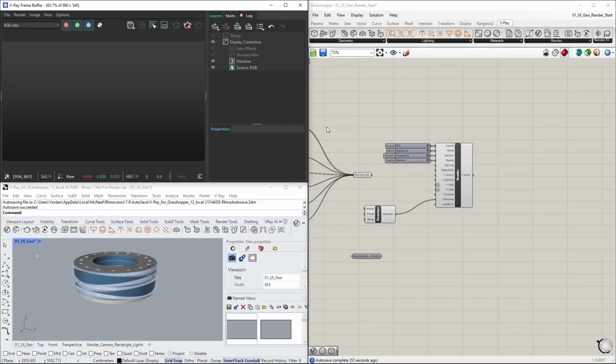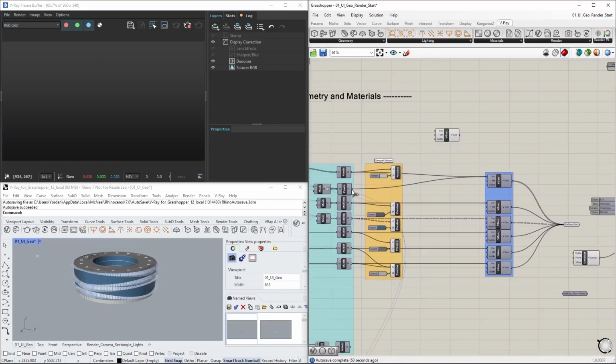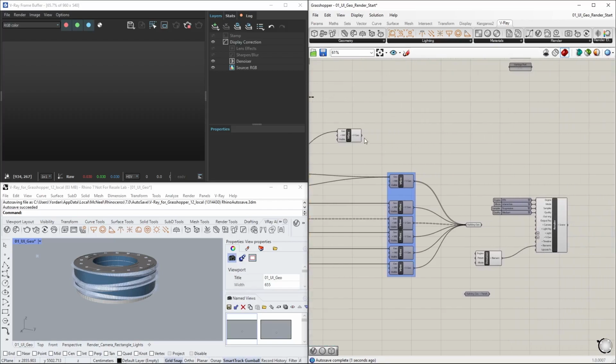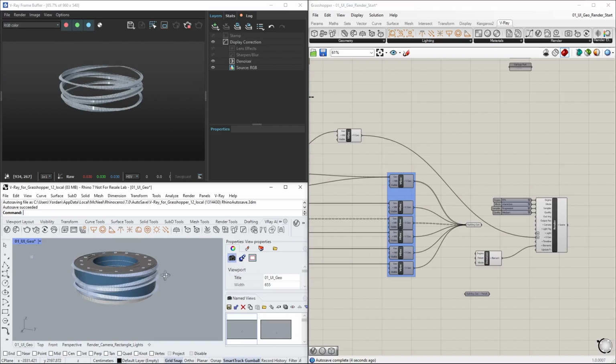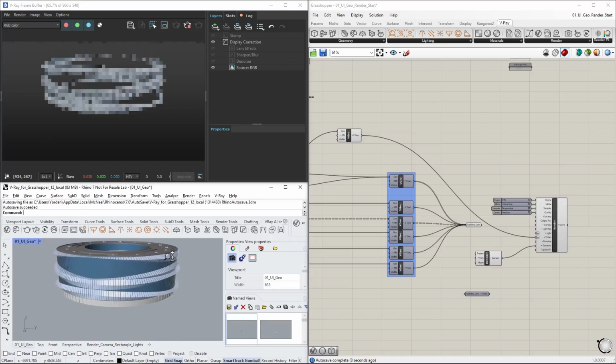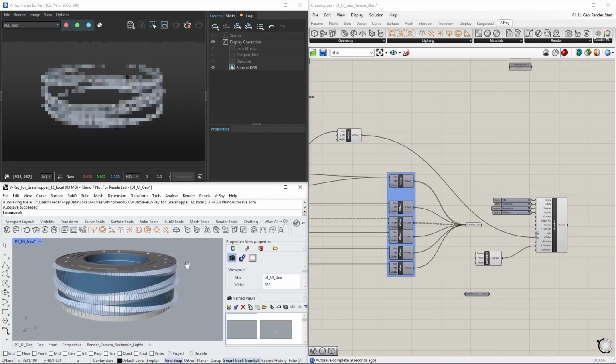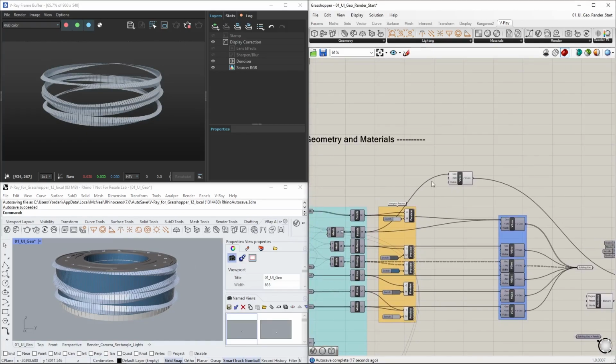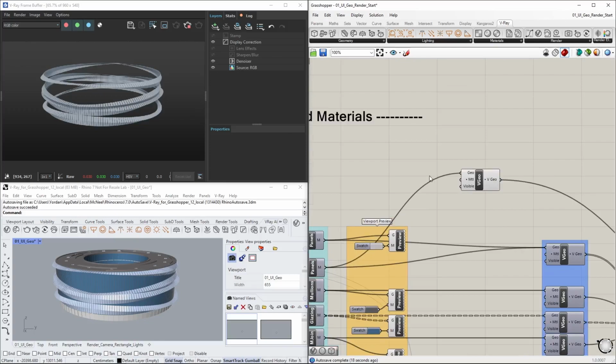The VFB is currently empty because the Grasshopper definition has to be connected via VGeo to the Render component. We render with RTX GPU engine in interactive mode, without baking the definition. This means that the definition is live and editable. By default, each VGeo has a generic gray material applied. You don't need to set material if you don't need it.